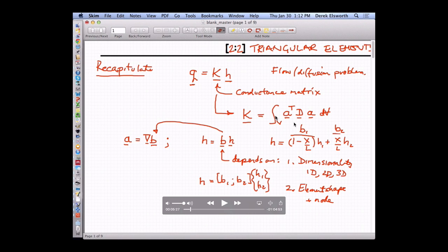So we'd have a different form of this A matrix if we're solving a problem that is either heat flow, fluid flow, or mass transport, Fickian mass transport, because all of those have as their variables scalar variables, which have just 1 degree of freedom per node, versus whether we're looking at mechanical problems, say in 2 dimensions, where you could imagine that we have displacements in the x and y direction. And so that's the basis of what this is.